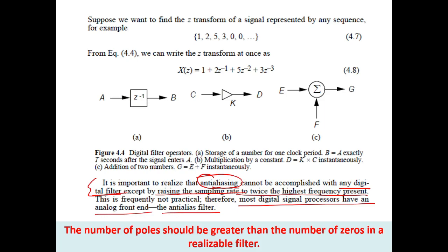Usually, it is the low pass filter of 500 hertz, so that even if you give a signal having frequency greater than 500 hertz, due to that filter, the maximum frequency of the signal will be limited, and the anti-aliasing will not happen. Okay, the anti-aliasing is on.